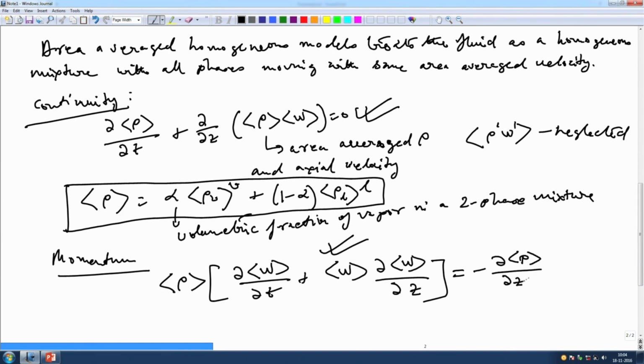This is P minus, if there is any gravity dependent gradient, that should be there. That is the inclination effect essentially, and then P by AC into tau W, where AC is basically the cross sectional area.